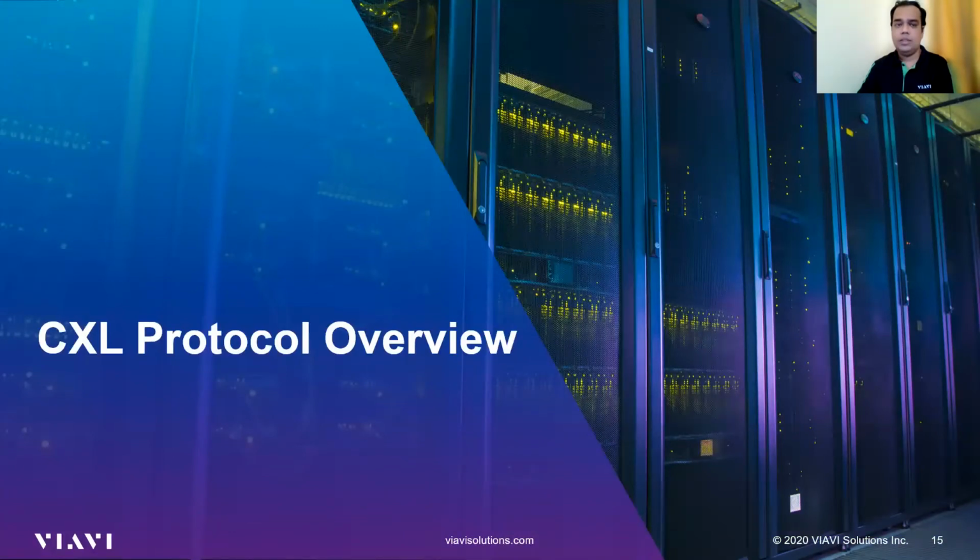The next one is the CXL Protocol Overview. In this section of the presentation, we will dive a little deeper into the CXL protocol aspects. First, let's go through some of the key features of CXL, like what makes CXL run over the PCI Express PHY and electricals, and then talk about how you can use the Xgig protocol analyzer to analyze the CXL link.